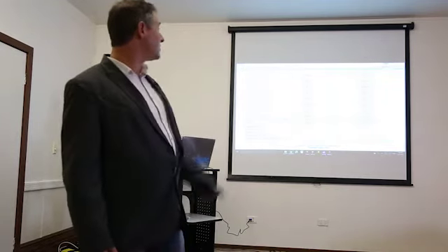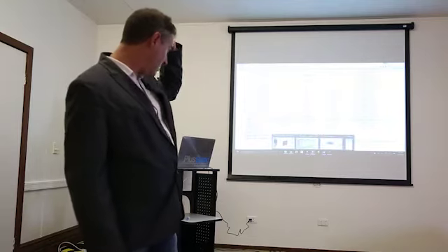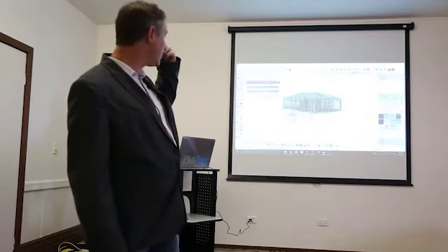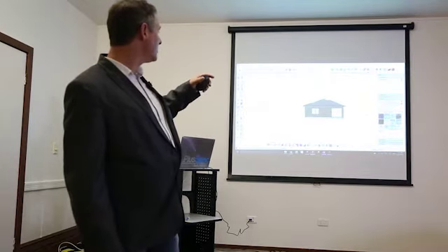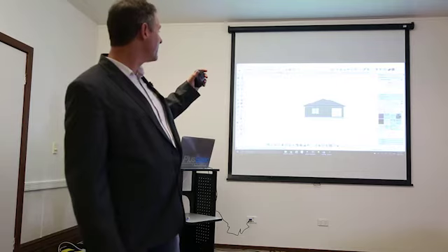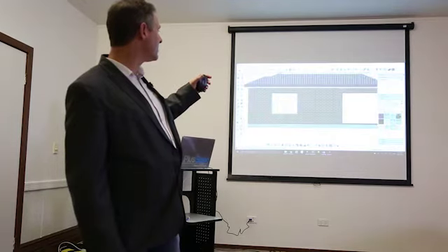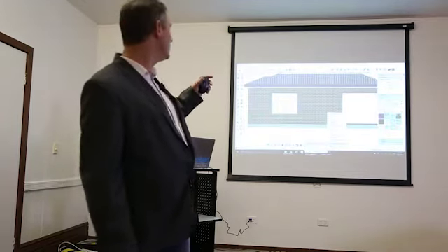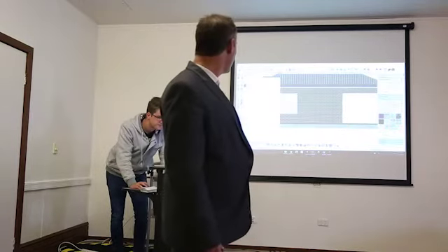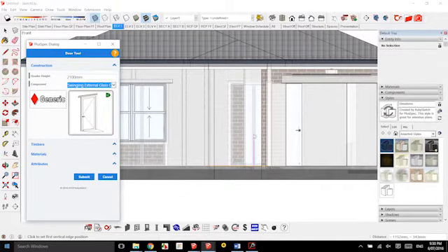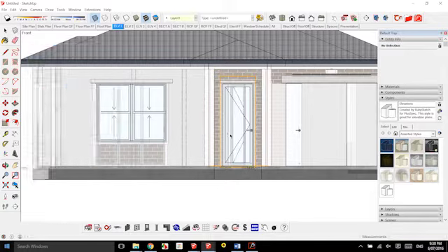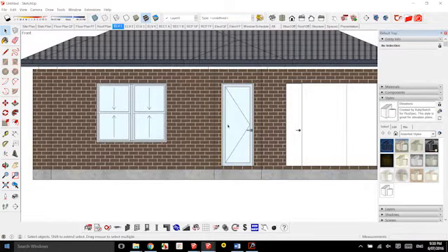All right, elevations. Can you do some elevations for me, Grant? From that plan, we now need to obviously create a set of 2D drawings. Delete that stuff. Zoom in, put a front door in. It's not a very nice house. We took this off Google. So hopefully it's no one's house here. Okay, right, now go to your elevations, put in black and white because everyone's used to seeing it that way.